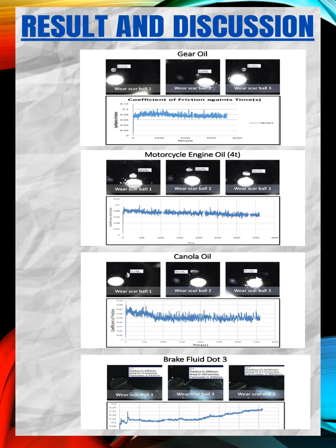However, although the gap between point to point friction is large, it remains constant and stable, which does not continue to increase and does not continue to decrease, like the reading on brake oil, whose reading is higher and overshoots when the RPM is higher. The results show that vegetable oils have a higher friction coefficient compared to brake fluid. Also, the wear scars produced by vegetable oil are slightly lower than those produced by brake fluid. It can be concluded that vegetable oils have potential as lubricants.